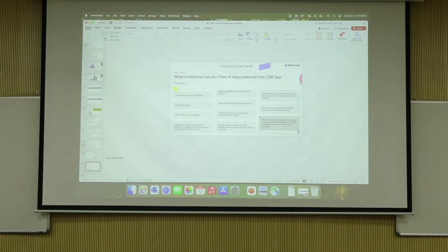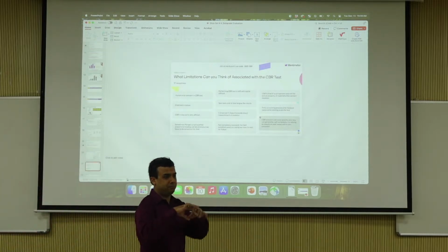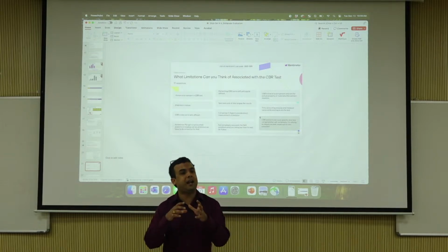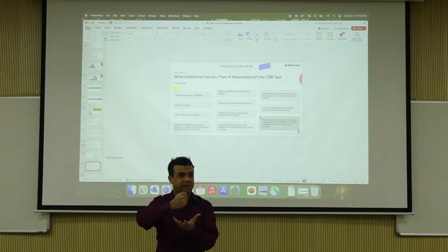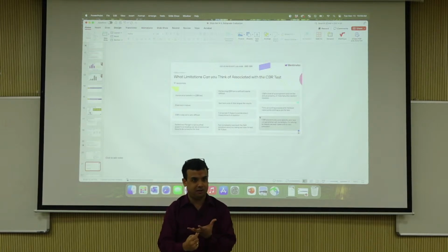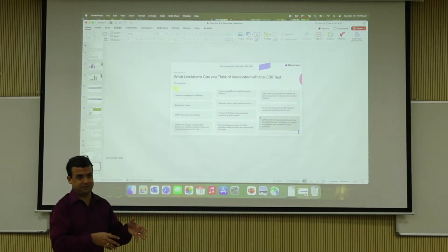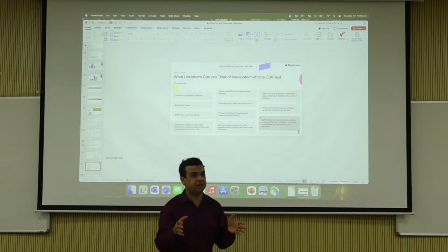So we have repeated loading of a tire, of some kind of a rubber thing, whereas you are trying to simulate that by taking a steel plunger and pushing it into a soil. And you are saying that we are going to get modulus out of this, because the mechanism is completely different, the loading phenomenon is completely different, right?